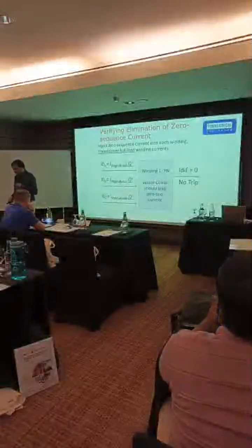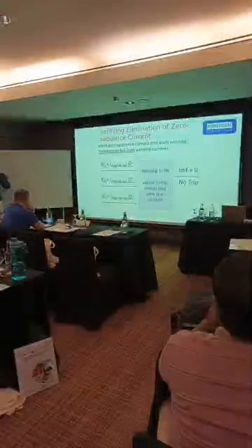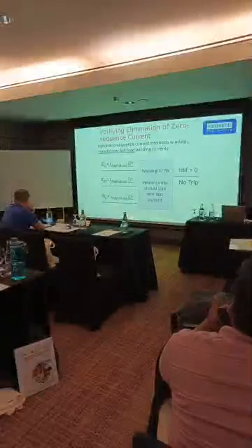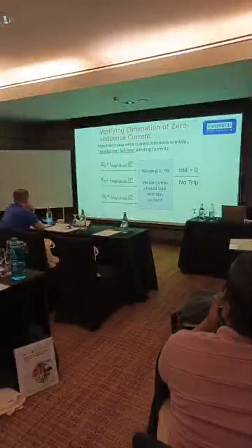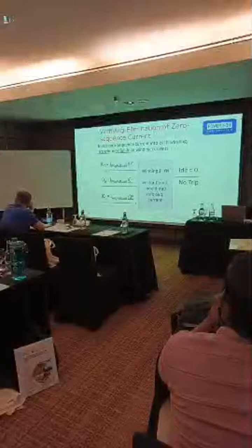So as he explained yesterday, was the pickup current. Suppose the differential setting is 0.3. This was the pickup value, right? Yesterday we took the reference of yesterday's setting only, so that there should not be any difference.